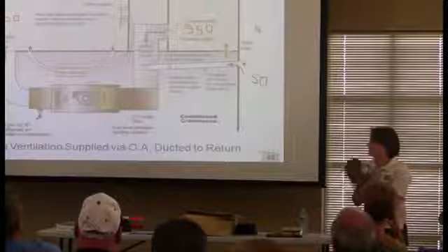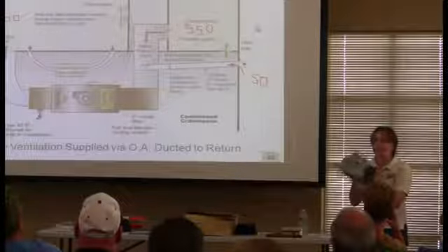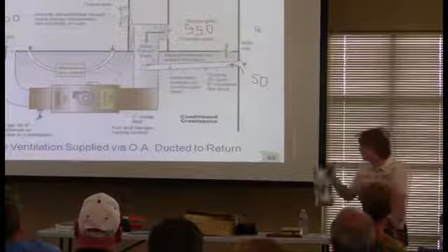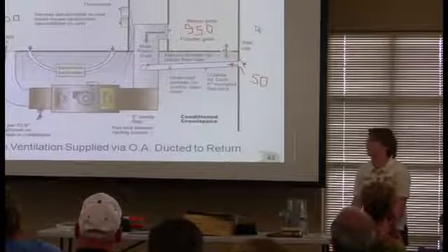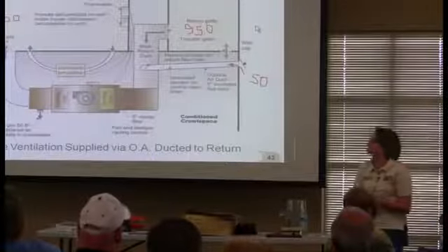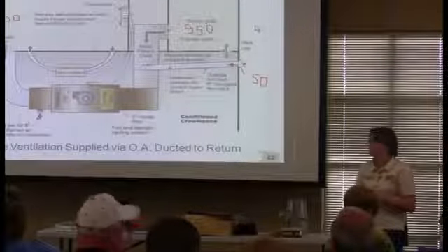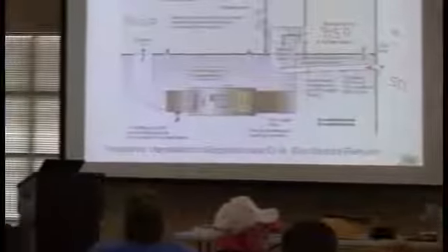So this system is basically just a 6-inch duct, this little mechanical damper, and a controller. All said and done, installed somewhere between $250 and $300. So it's a really cheap option. But it's a great way, if anybody ever says, I'm worried you're making my house really tight, you can say, well, I've got intentional ventilation.